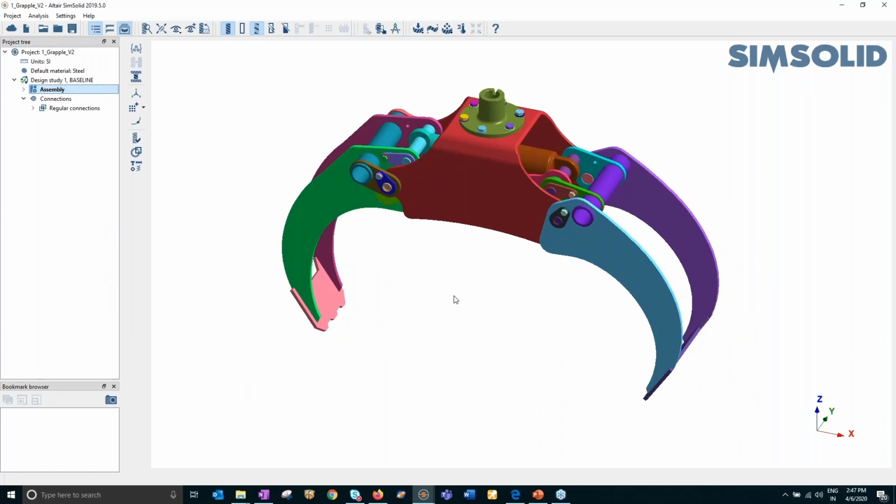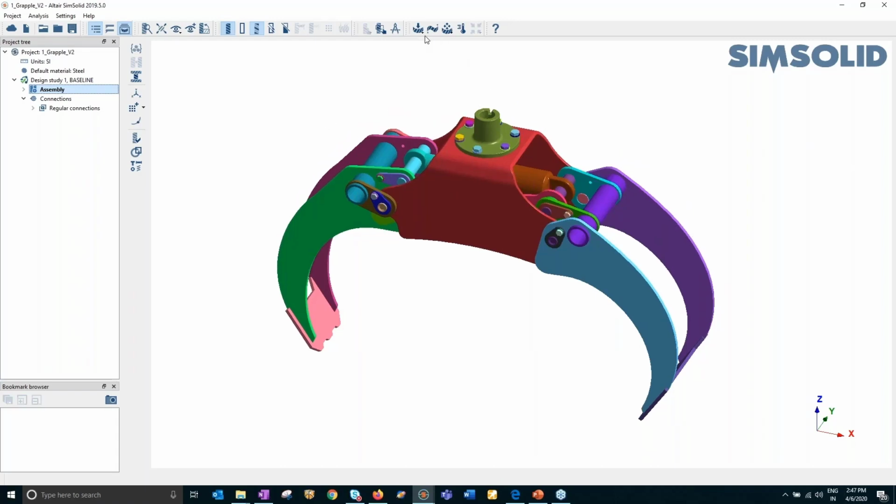Next, as soon as your material definition is done, you can choose the type of problem you are going to solve. Again, this is quite rich. Although this is a very simplistic GUI and looks very simple, it is quite powerful in terms of the physics it can solve. For example, it can solve linear structural, non-linear structural, which includes contacts, geometry, and material non-linearity.